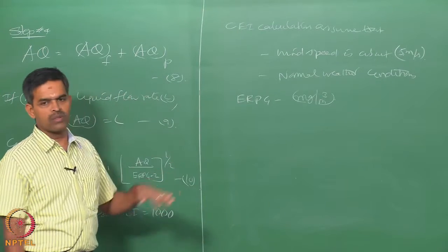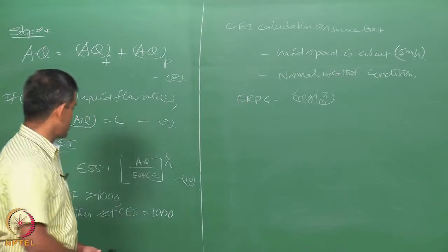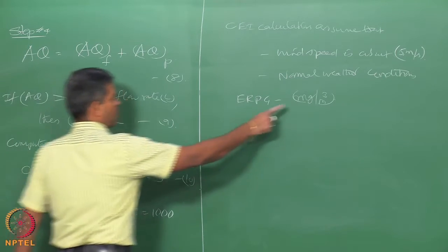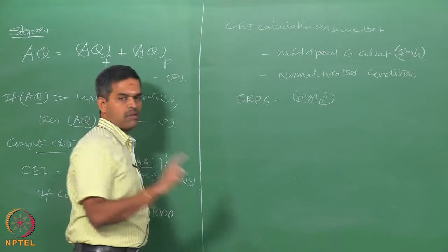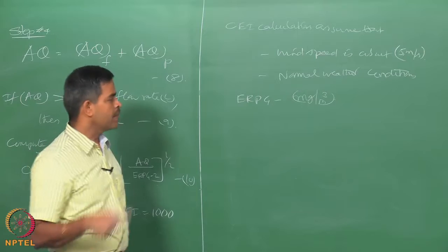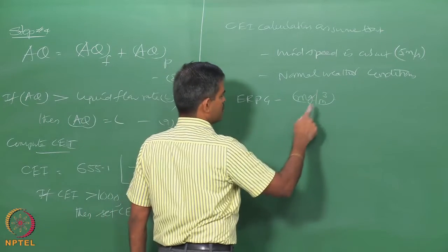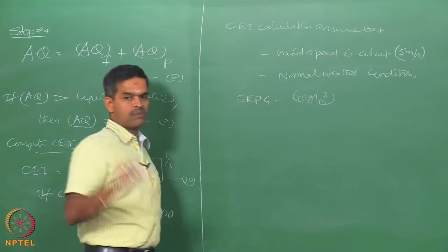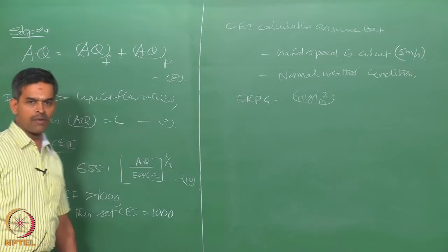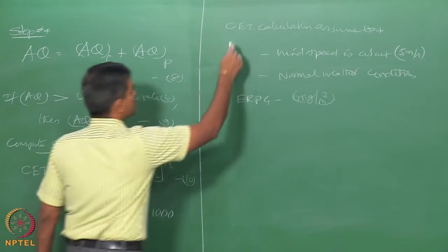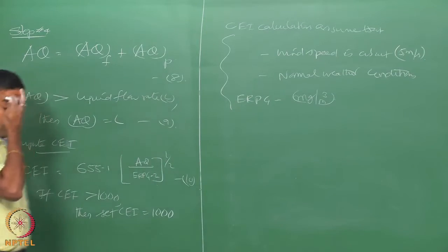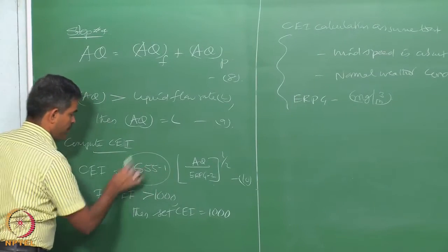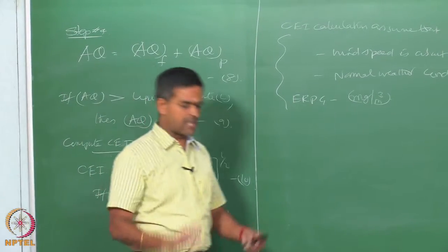That is level 1, 2 and 3 respectively. So, you have to substitute that value in milligram per cubic meter. Please look at the concentration available in the tables of the chemical engineering handbook. Sometimes it can be of a different unit. You have to take the ERPG value for a specific concentration in milligram per cubic meter, because all these constants are taken care of in this number. So, we have to substitute only these exact units.